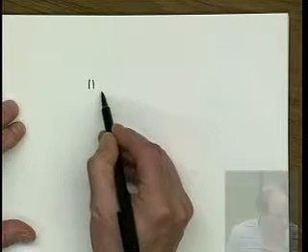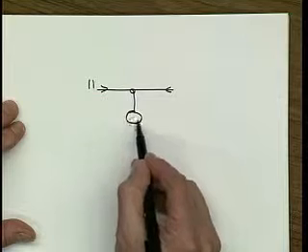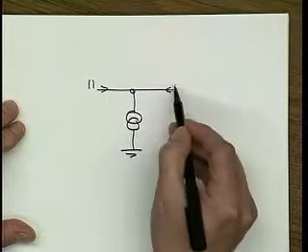For that we will go over two things today. One of them is this business of differential input, and the other one we go at a more general amplifier, folded cascode, as an example and very common workhorse amplifier. So why would we rather have a differential input than just a single common mode? Well, there are a number of advantages to doing that.